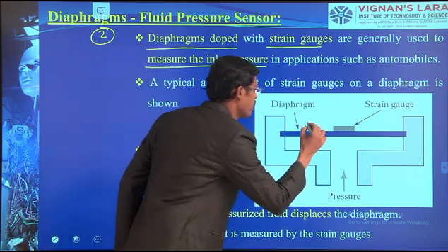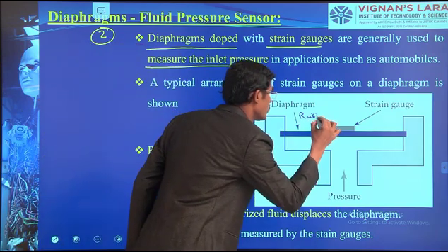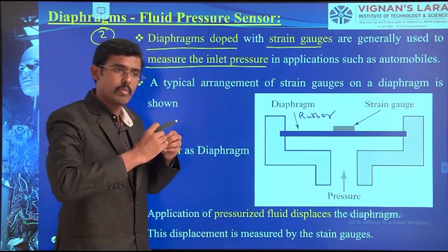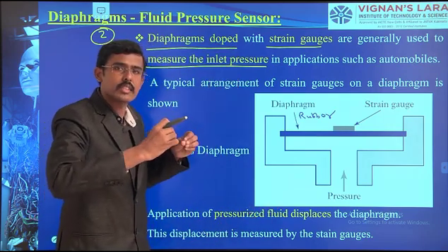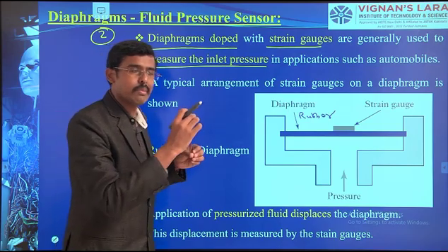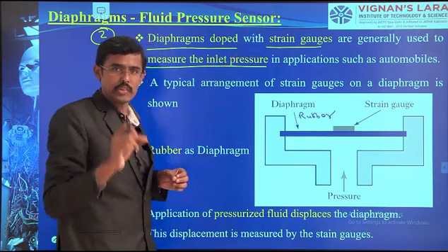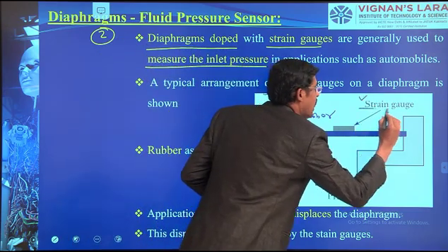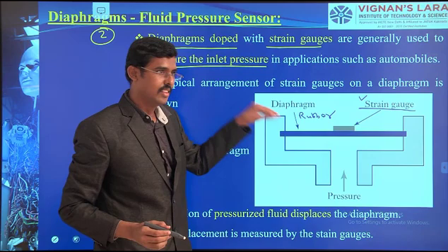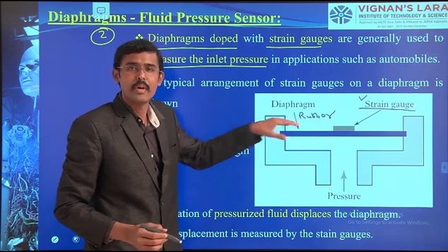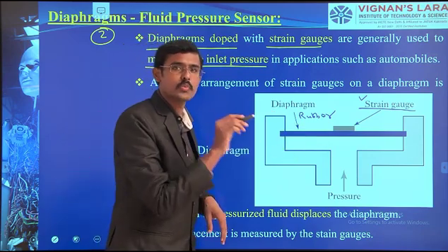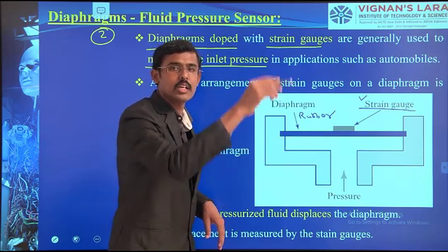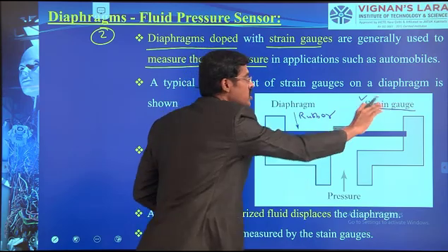With the rubber diaphragm component, elastic deformation occurs. But for the measurement system, for the closed loop, we are adding the strain gauge here. Additionally, when the change in the diaphragm happens, the displacement or the pressure applied is converted into electrical format through the strain gauge.